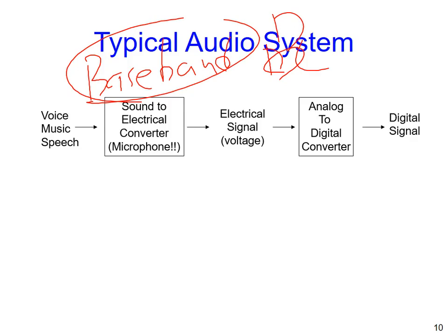Compression, encryption, low-pass filtering. From the very beginning, they need 8th order low-pass filtering. Is it easy to realize in the analog domain? No. According to device mismatching, forget about it. For the analog domain, I guess 2nd order is good enough. How about 3 or 4? Forget about it. You will get too much mismatch, which destroys the filtering property. So it is only possible in the digital domain, because in the digital domain, everything is perfect. Everything is ideal. You can do anything as you like.